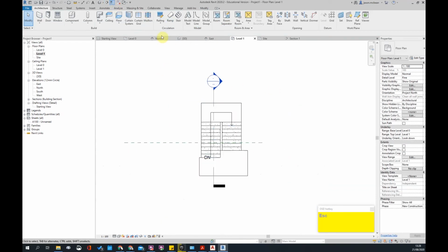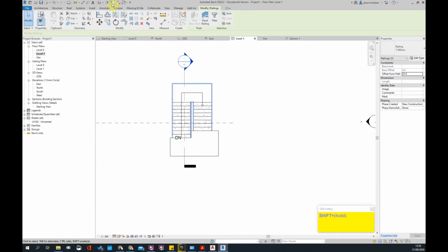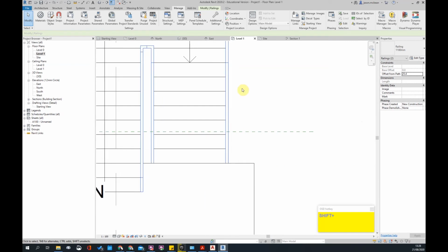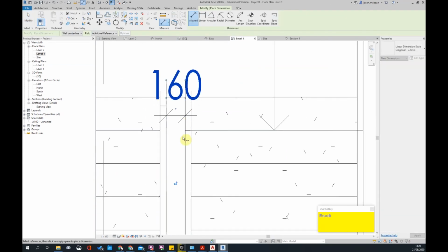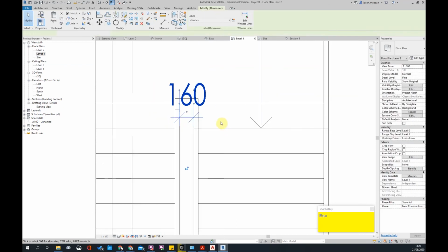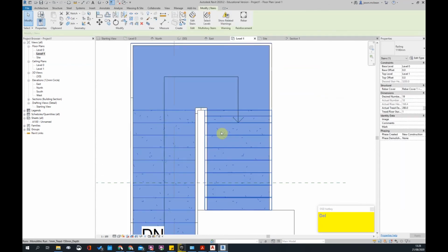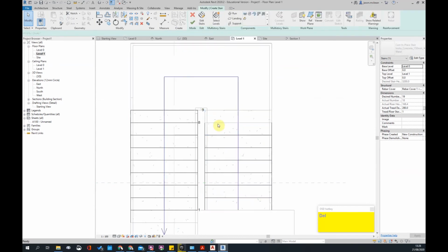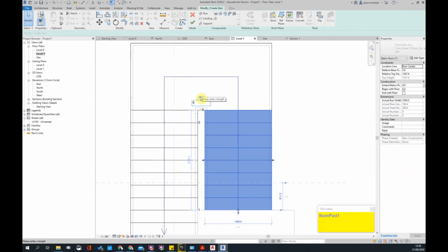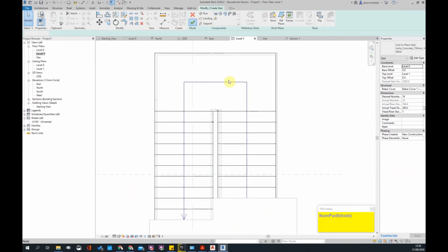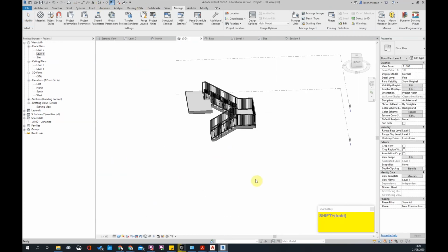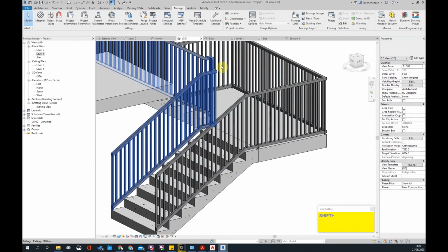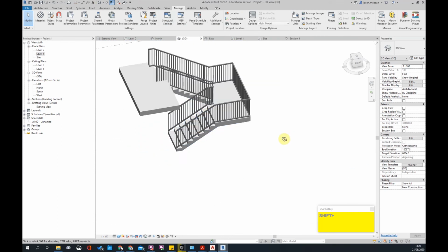Let's go to 3D view. So if I want to put a railing on the step now, you've got enough space here so your hand doesn't, you want about 120 mil between there as a safe distance. So I could in theory go and say edit stair, and then this distance can be 120. Okay, finish. So now your hand is safe, so your hand will be generally quite safe when it goes around that railing there.